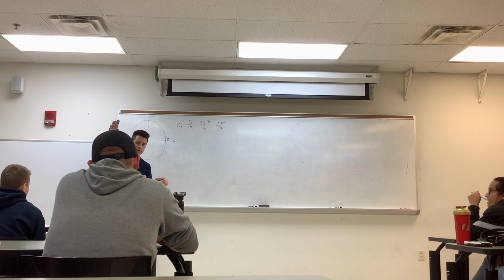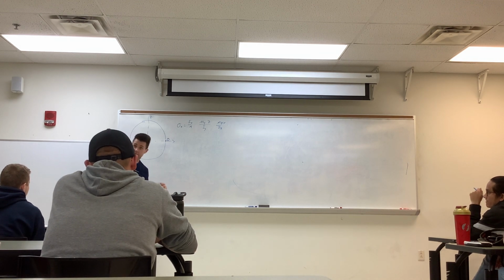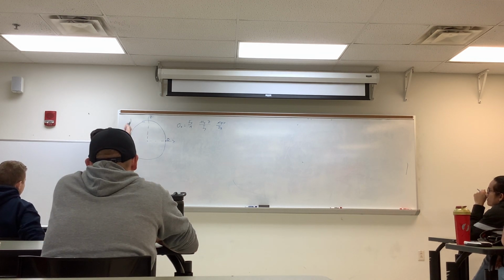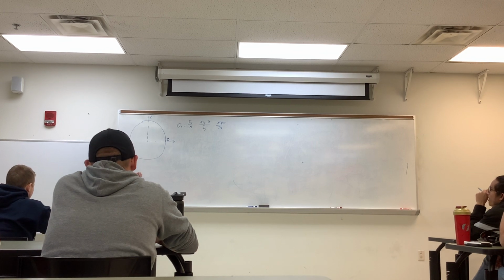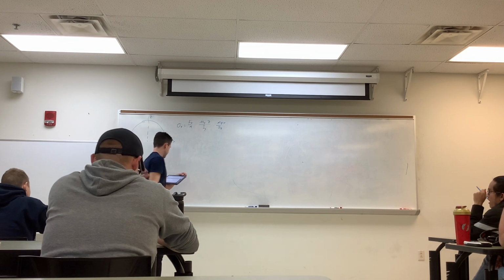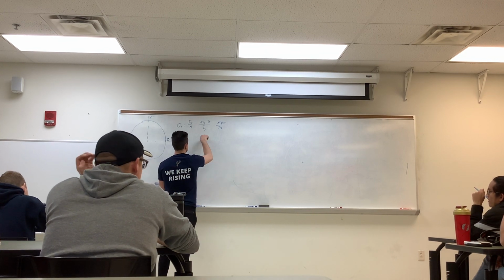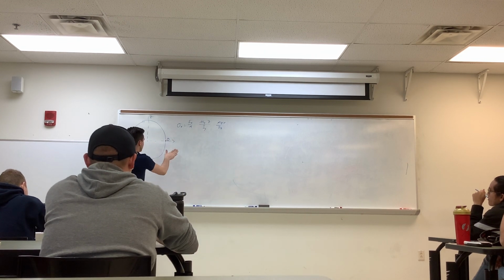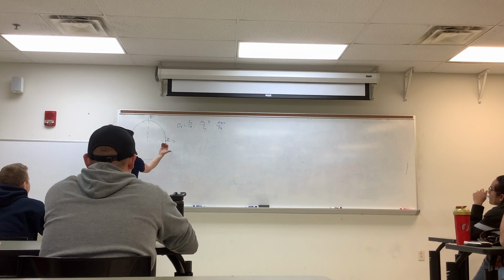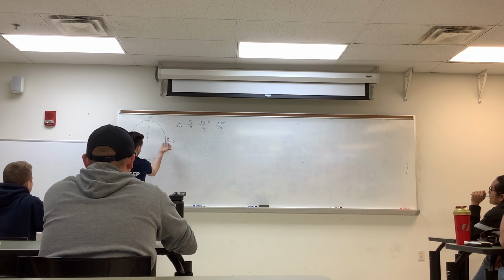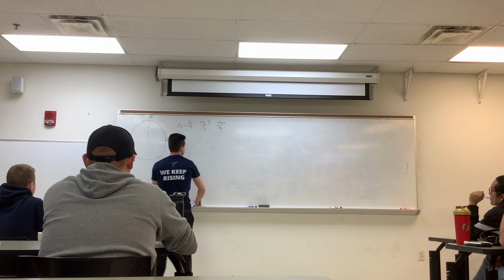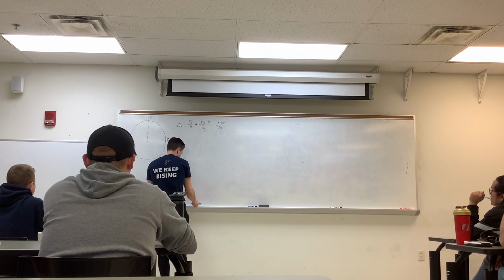So in this situation, F of x is coming out of the page. The z-axis is up, the y-axis is to the right. First off, doing that right-hand rule, I'm going to start with M sub y. Along the positive y-axis, we're looking at point D, but since it's also along this y-axis itself, it is still going to be in tension at that location, giving us this to be positive.